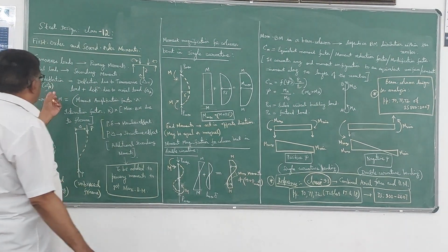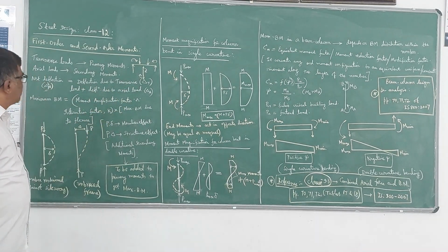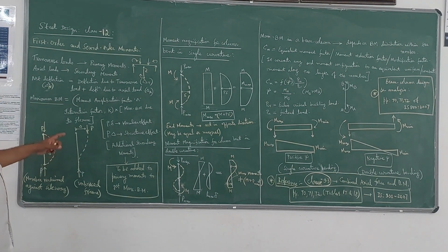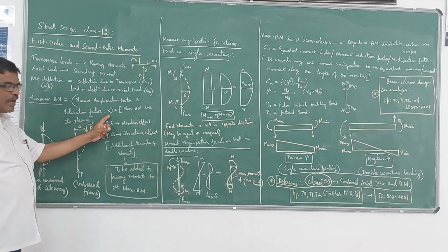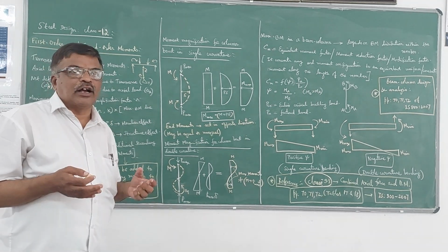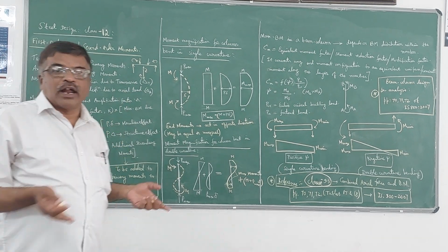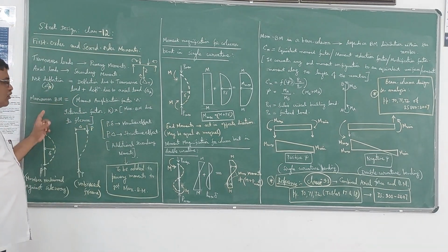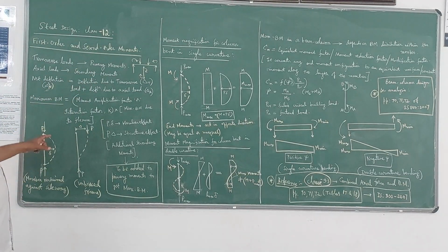And the net deflection, the total deflection, will be deflection due to transverse load plus deflection due to axial load. So the maximum bending moment in the case of beam columns is nothing but the moment amplification factor or interaction factor K into the maximum bending moment due to flexure. That means whatever maximum bending moment you get due to this transverse load, that is the bending moment due to flexure, has to be multiplied by an amplification factor or an interaction factor called K to get the maximum bending moment due to the effect of both primary as well as secondary moments.